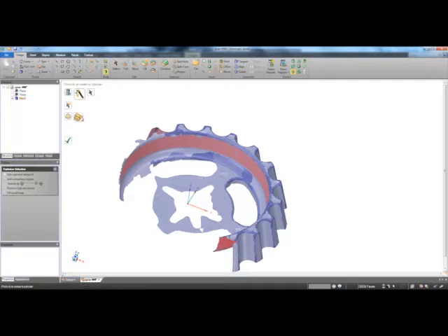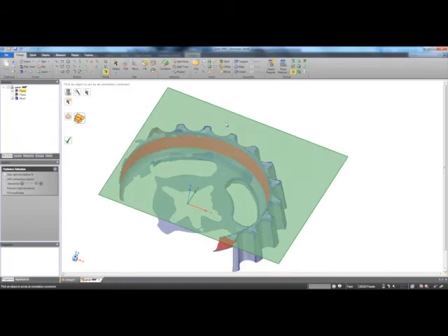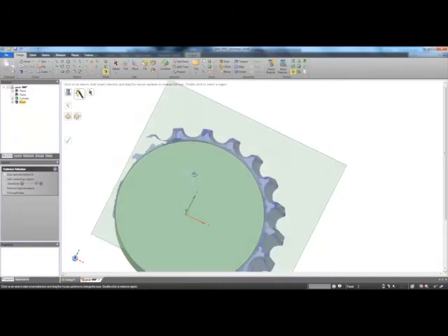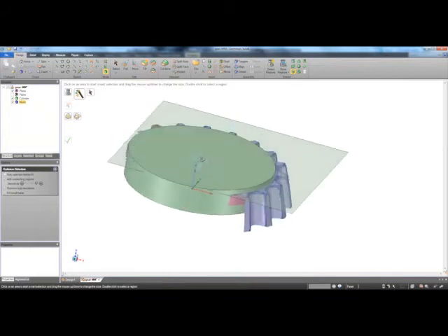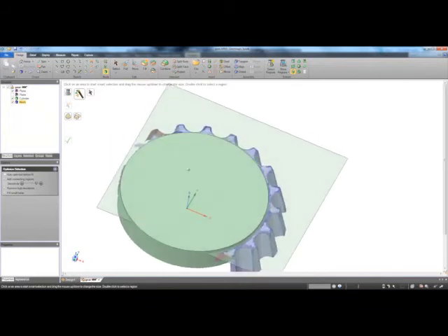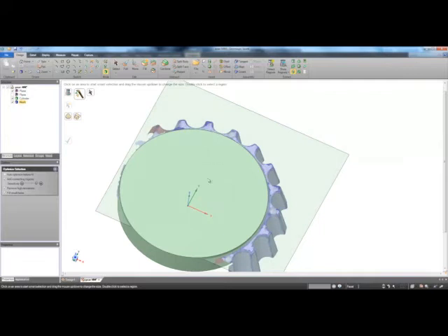It just makes your selection process a lot easier. And for fitting, I can also constrain. I can constrain the orientation, or I can constrain the position. In this instance, I'm just going to constrain the orientation. I'm going to show that top plane because I want to make sure that it's orthogonal to this plane. So I'll choose that, say Optimize Selection, and then complete the fitting. So now I have a cylinder that has an axis that's perpendicular to that top plane, and I can use this cylinder to do my alignment as well.